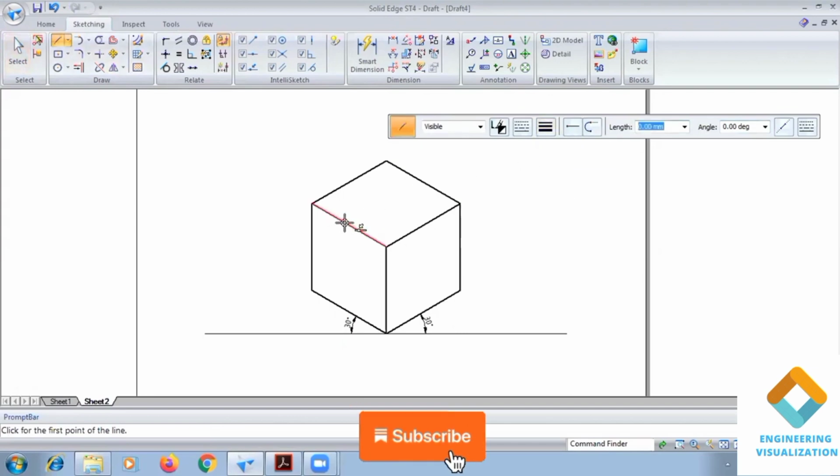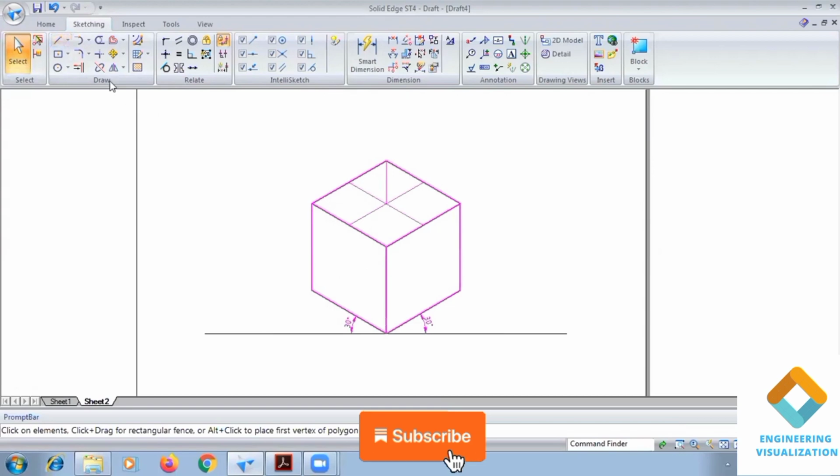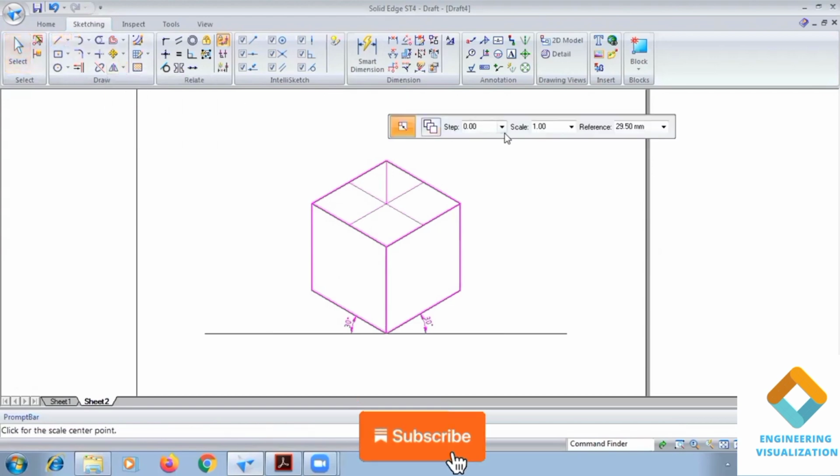So find out the midpoints. The height we need to find out. This is the center of the box. The center of the sphere will be found. The height will be 25. Now after finding the height, we will convert into iso. So this step you remember, guys. Go to scale here, type 0.816 or 0.823, you can type it.